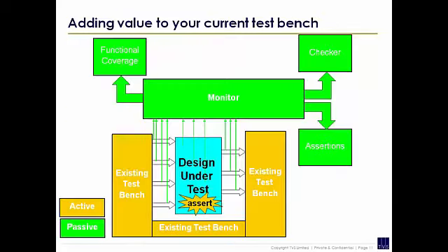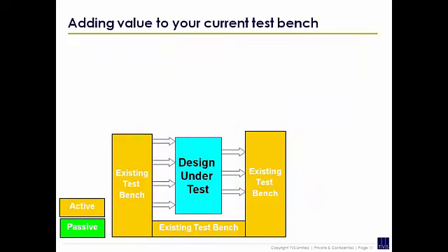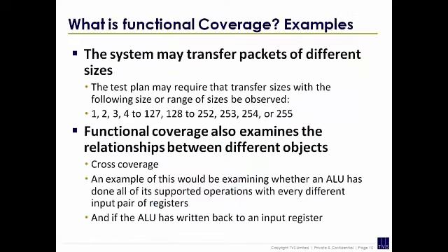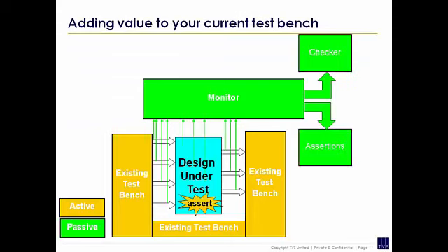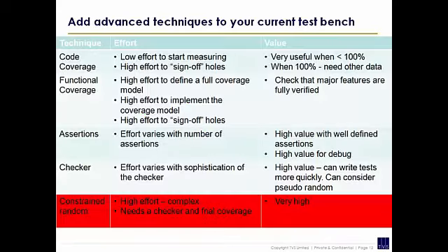So if somebody comes back and says, right, I've now got my test bench and I've written to all these addresses. Okay, normally you may go in and do a code review to make sure the test bench is really doing that, but you could also do it by functional coverage, by looking at the functional coverage point and generating the functional coverage to make sure that person has implemented those tests correctly. So you could add in functional coverage here just to check that the tests are doing what you think those tests are doing. You can do that without disrupting your current test bench.